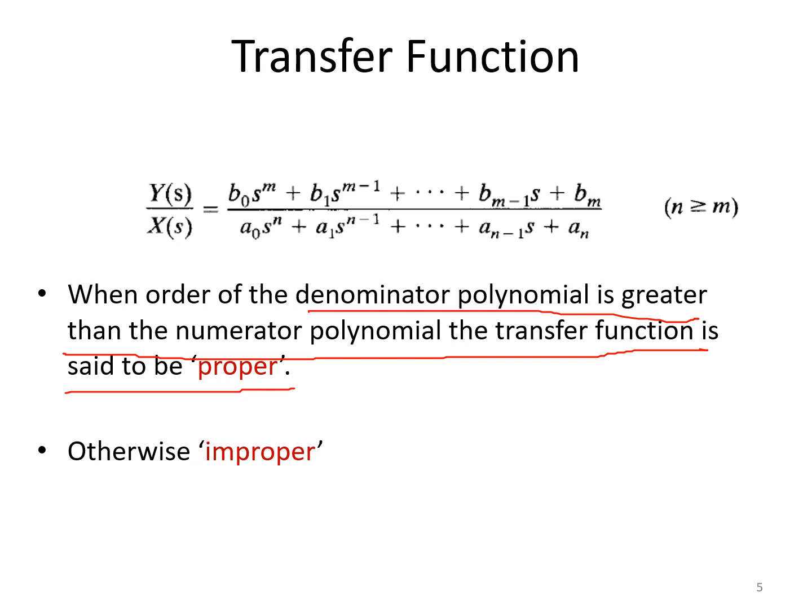That means if the numerator polynomial power is greater than the denominator polynomial power, then it is considered to be an improper transfer function which cannot be analyzed, and you need to convert it into a proper transfer function, and then you can factorize and analyze the system. This is another important thing what you need to know with respect to transfer function polynomials, proper and improper.